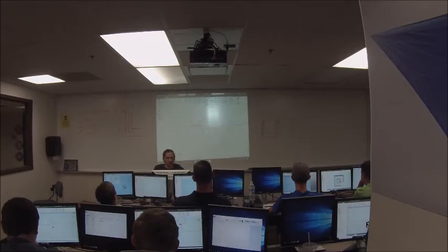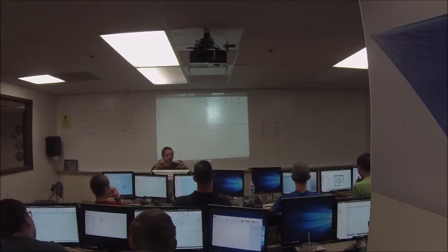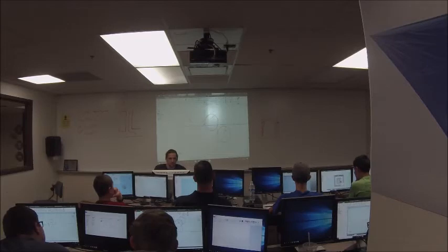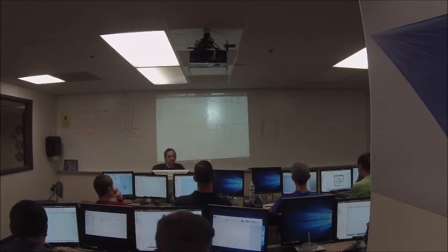So now if I make a dimension here and I dimension this circle and I say, hey, I want this thing to be 4 inches, the other circle will change sizes. Then if I change this and go 3.5, the circles change sizes. And because these lines are unconstrained, they're kind of floating around, and Inventor's doing stuff with those as well, but that's just because they're not constrained.